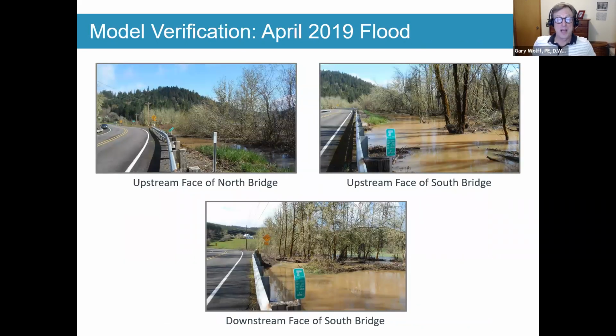So the next thing I'm going to show you guys real quickly is, when you're doing hydraulic modeling, you ideally like to calibrate. We didn't have detailed calibration information here. There are no stream gauges, so we're estimating the flows, like I said, from StreamStats. And with no gauges, we don't have a record of flood levels in this area. So all we have is anecdotal information that this road overtops every few years.